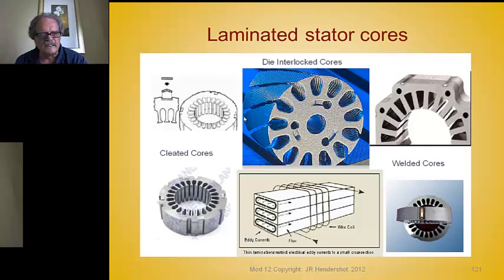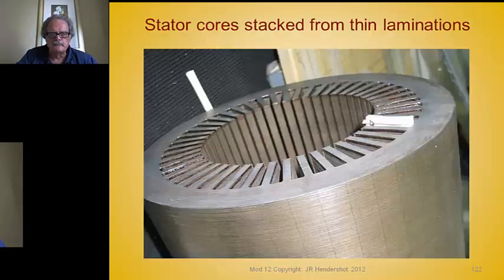Now, I think it's important to note here what a bad job this is. You see, that skew is not uniform. See all this jaggedness? Well, that cuts into the slot opening. If this is an induction motor, then you've reduced the cross section of the die-cast aluminum material. That's a very bad job. That die needs maintenance. The servo system that does the rotating of that interlocking notch needs attention. It's a very poor job. I'm happy to have this picture to illustrate that to you.